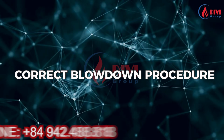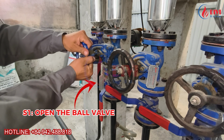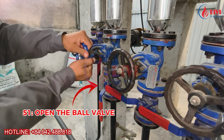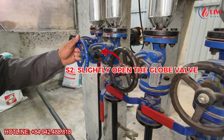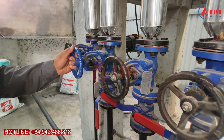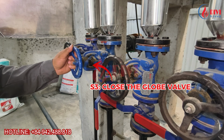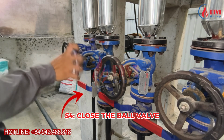Correct blowdown procedure, critical. Now let's go through the correct manual blowdown procedure. Step 1. Fully open the ball valve to ensure the blowdown line is clear. Step 2. Slightly open the globe valve to allow a small flow of water to pass through. This helps to preheat the piping, allow uniform thermal expansion, and prevent thermal shock during full discharge. Step 3. Once the piping is hot and water is flowing, close the globe valve. Step 4. Close the ball valve to prepare for the main blowdown.